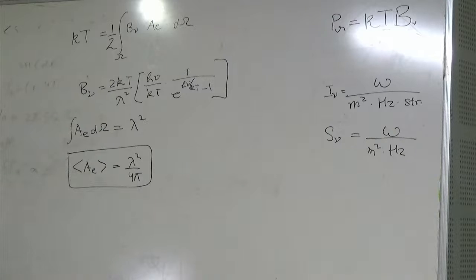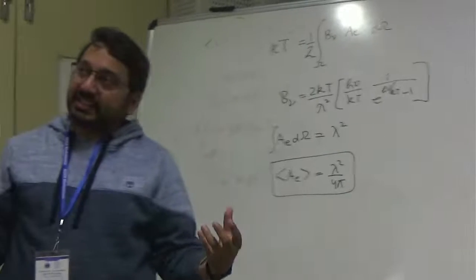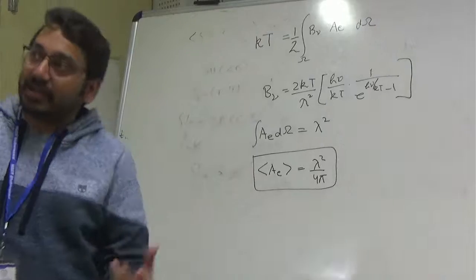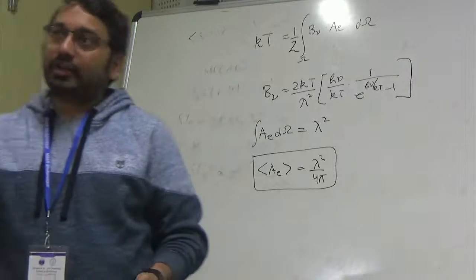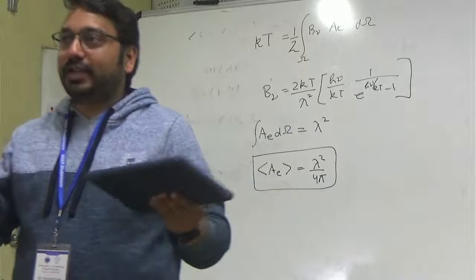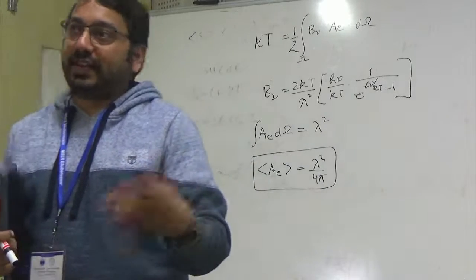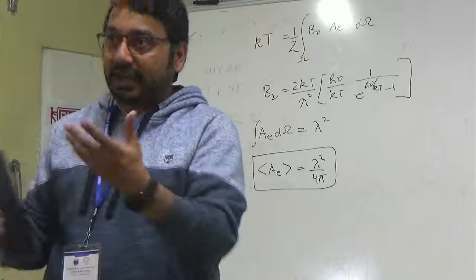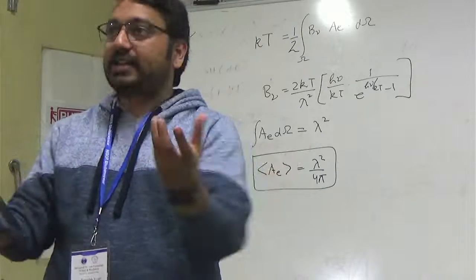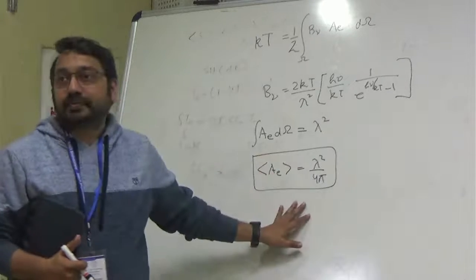frequencies. And that's why you see, for example, MWA, these are dipoles. And they are very discrete systems. They are what we call elemental antennas. On the other hand, when you look at SKA-Mid, these are dishes. Why do you think at higher frequency we go for dishes, and at low frequencies we can live with these small antennas like MWA, low power? All of these are elemental antennas. And the reason lies here.